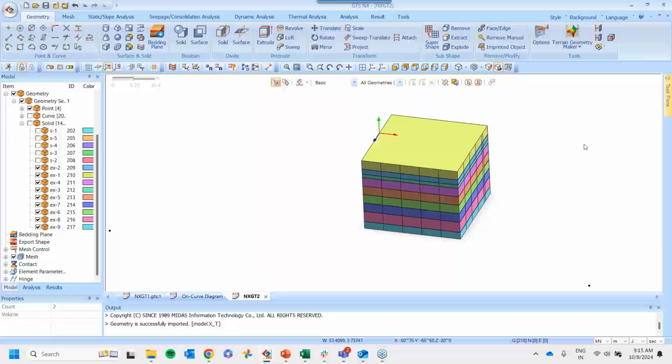Now, the embedded depth of a wall depends upon a lot of factors, like the width of the wall, the type of soil or rock which is there, the type of excavation. These are certain things, and also there are codes where certain country codes have clearly defined the minimum required length of embedment.